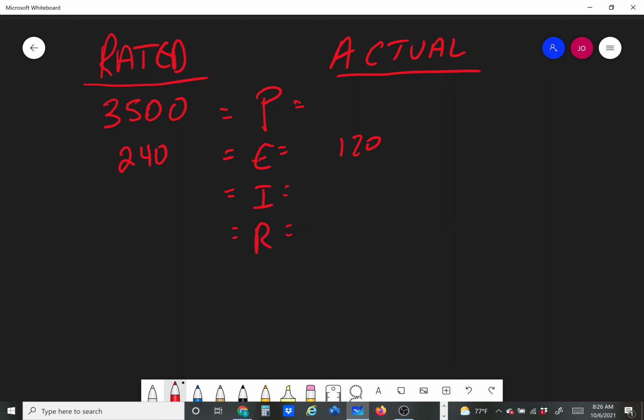That is E squared over P equals R. So if you plug in, E squared over P, you get 240 volts squared divided by 3,500 watts, and you get 16.457 ohms, which is what you'll have over here, 16.457. It goes out a little bit further, but that's all I'm writing down.